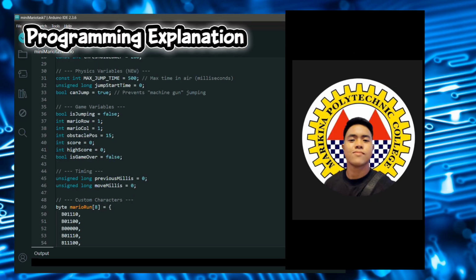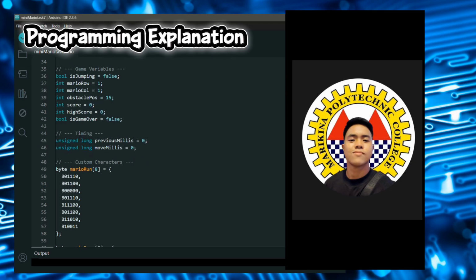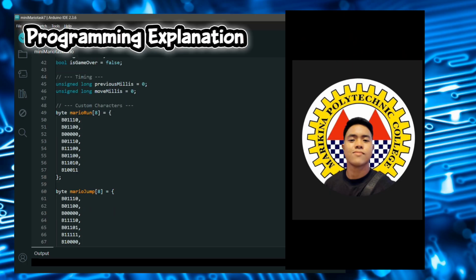In the setup function, we initialize the I2C communication using lcd.init. We also configure our inputs. For the joystick button, we use INPUT_PULLUP. This utilizes the Arduino's internal resistor to ensure stable digital reading without needing extra external components.